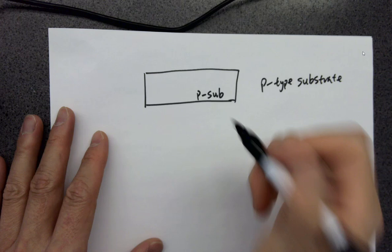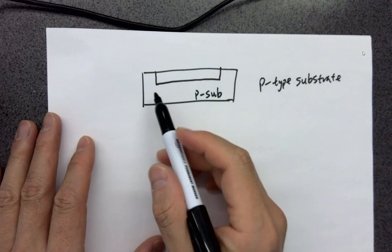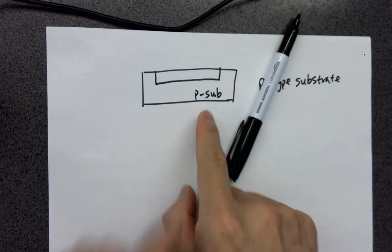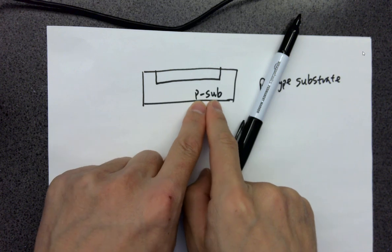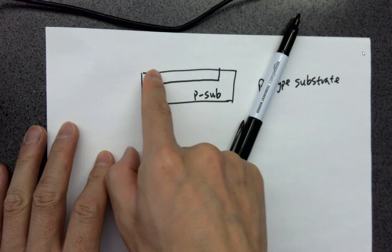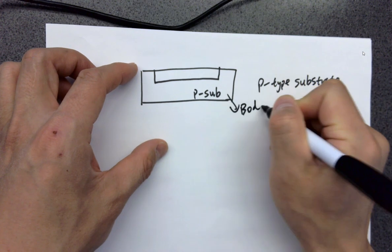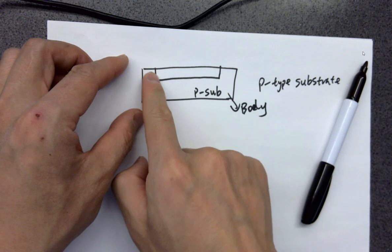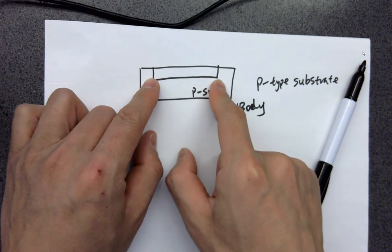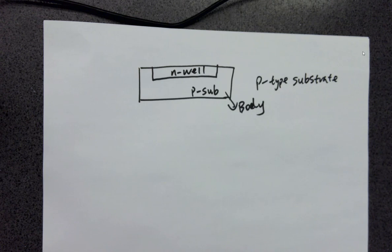P-type substrate, and if there's the N-well material being doped into the P-sub material, it's a silicon wafer, and it's being doped slightly with a P-type material, so it's called a P-sub, P-type substrate, or P-sub, and that's the wafer body itself. Sometimes we call this body. It's a really weird term, body, and we dope an N-type material into the P-sub to form an N-well.